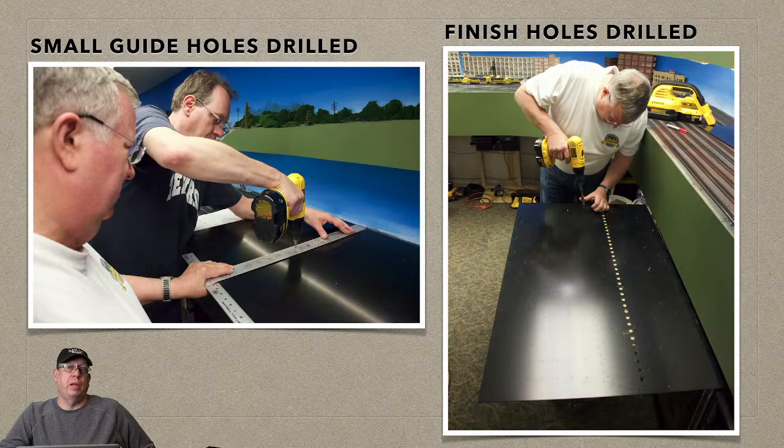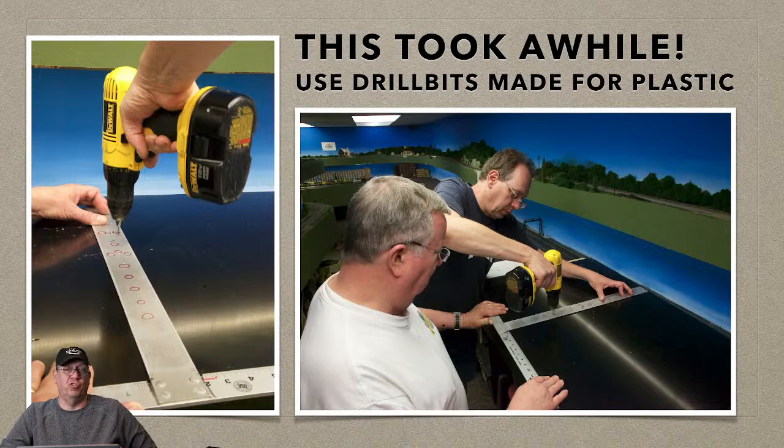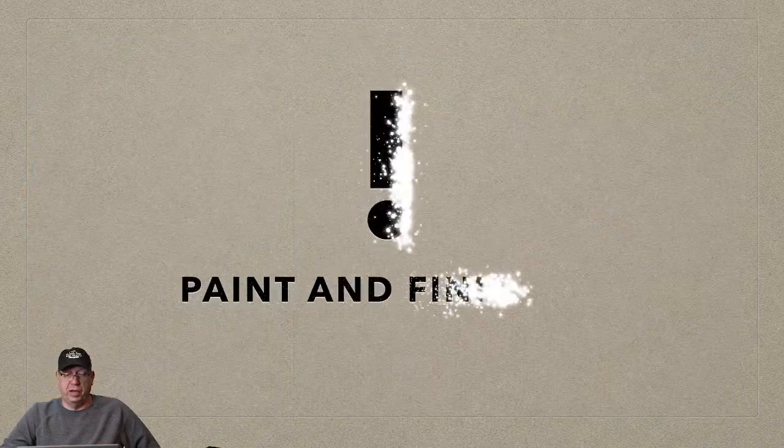By the way, when you're drilling plastic, please go out and get some bits that are made for plastic. They have a different tip shape, and they're far better than trying to use a metal bit or a wood bit. They have a very sharp, steep point on them, and they cut your plastic much, much better than any other drill bit. I didn't even count the holes, but I bet there's 900 or 1,000 holes on there. On that left image, you can see the machine being drilled, and we're drilling out the face panels for the CTC panel.